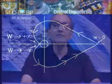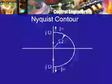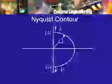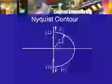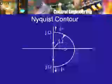Now, this is a plot of KGH(j omega), and if you go back to the Nyquist contour, the Nyquist contour consists of a part of the j omega axis closed by what I drew like a semicircle in the right half of the complex plane. In other words, this part corresponds to minus j omega to plus j omega, and then there is a circle of radius, say, omega, and the argument changes from pi by 2 to minus pi by 2 in the clockwise sense.